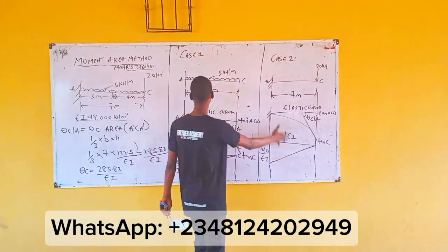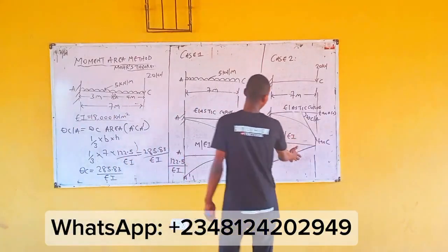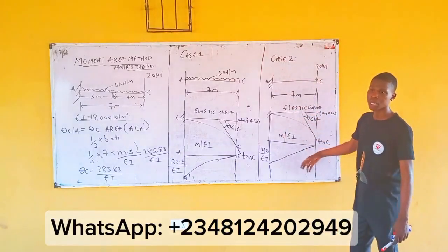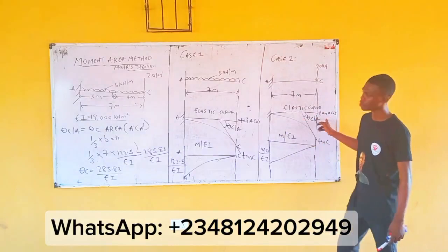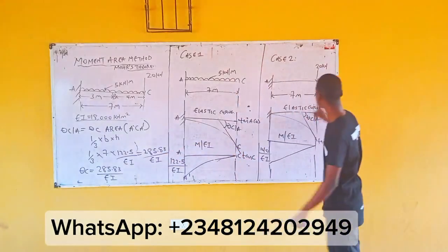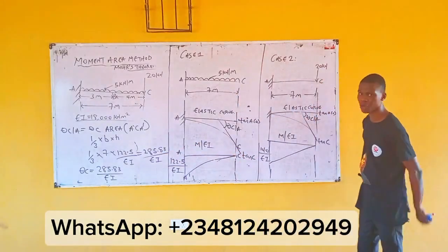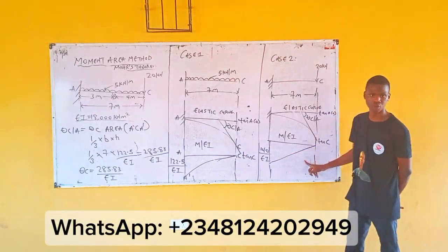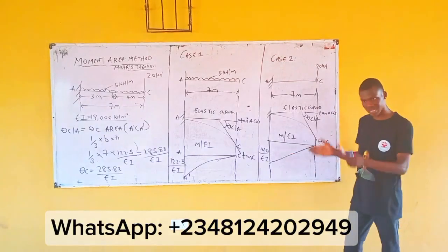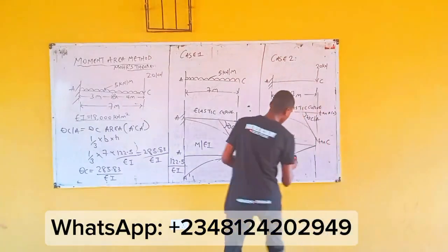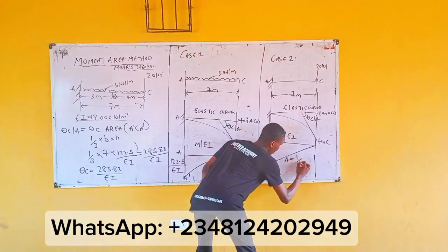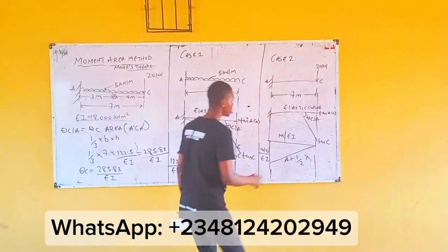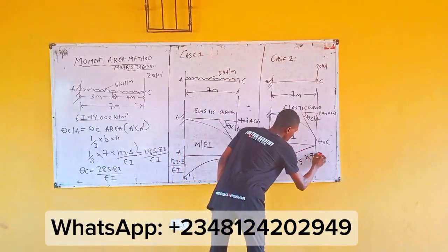So let's just solve for the area. Let's just find the slope at C, right? This is the same idea. In this case, to get the slope at C here, that would be the area of this shape. This shape is a right angle triangle. What's the area? 1/2 times the length times the height. Now, meaning the area here is 1/2. What's the length? 7. The breadth, what's the breadth? 7. What's the height?